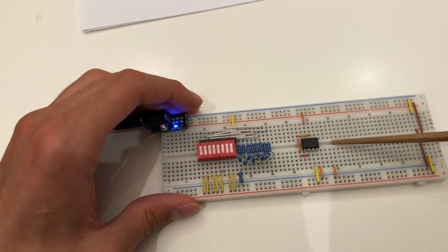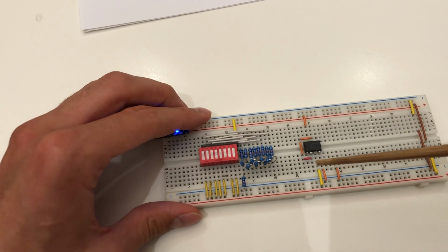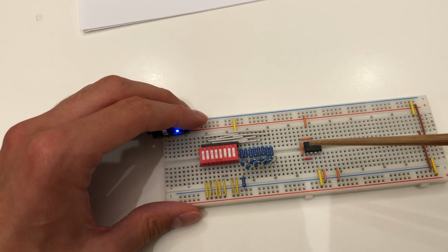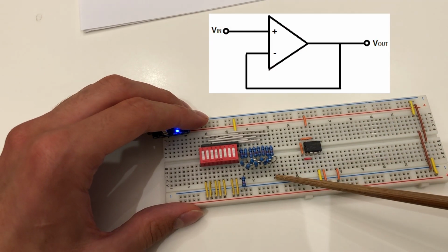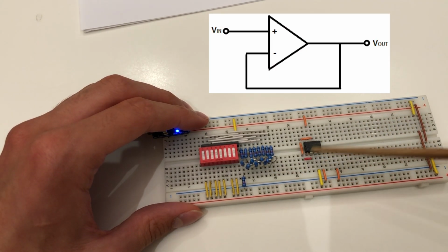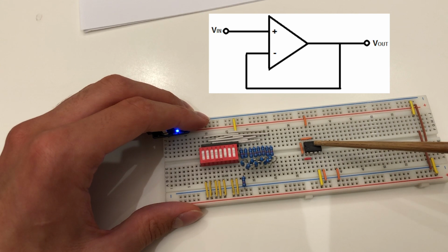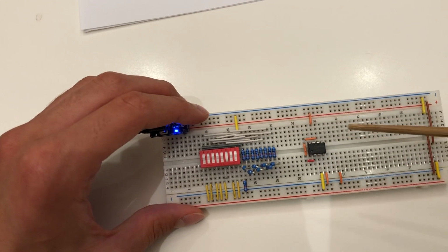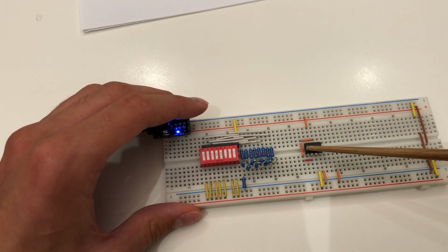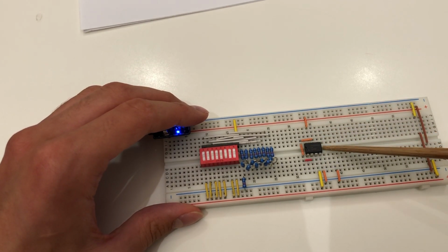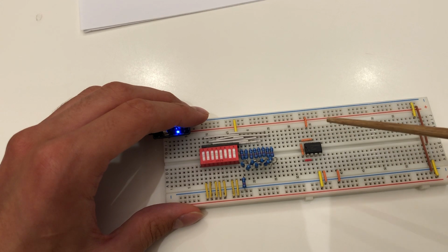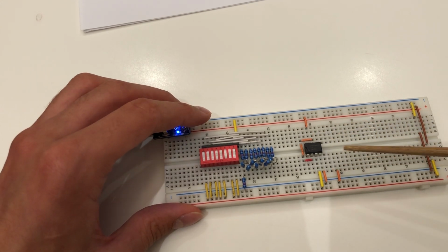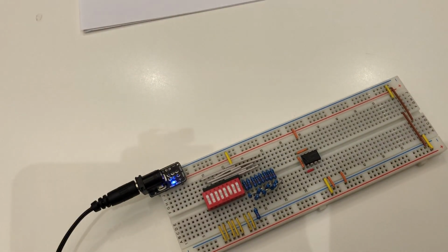In general though, the problem with the R2R ladder is that the current is diminished at the end of the circuit. So a voltage follower using the LM741 op amp can be added to turn a high impedance on the input to a low impedance on the output. Though it sounds great, there's actually a problem. The 741 is not a full rail-to-rail op amp, meaning some values cannot be exceeded or gone under with a 5 volt source. And it has a voltage swing of around 1.8 volts to 5.2 volts.